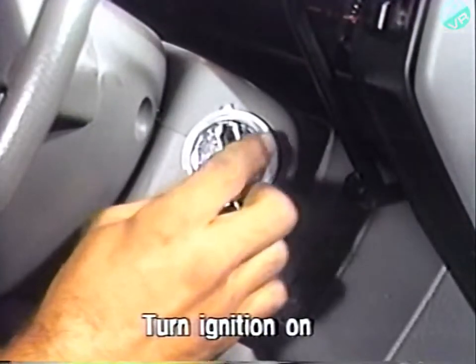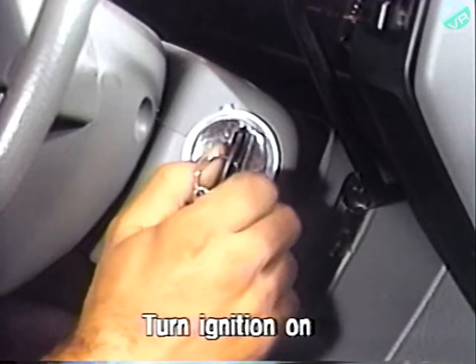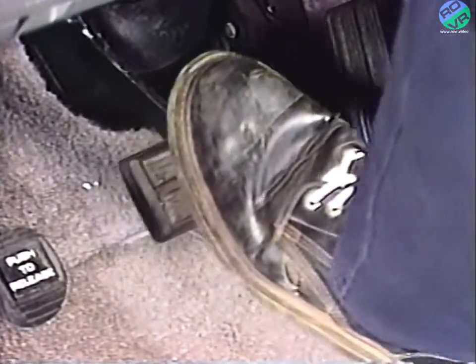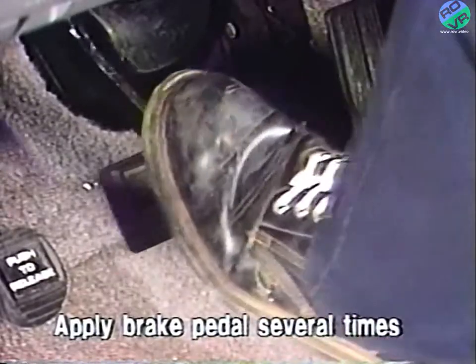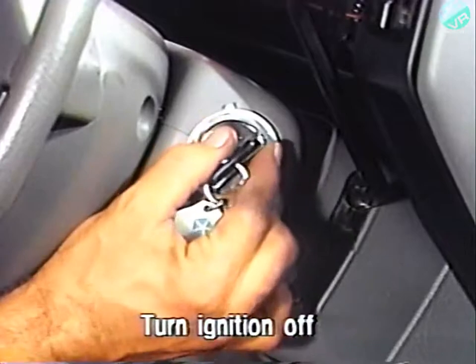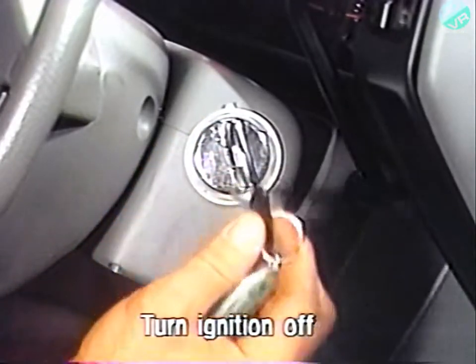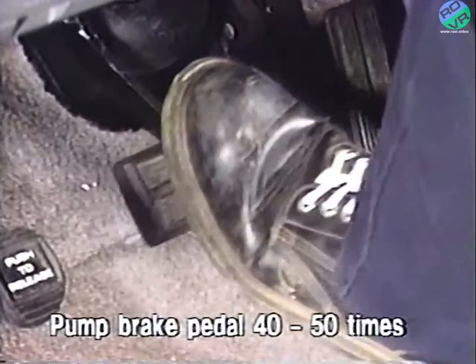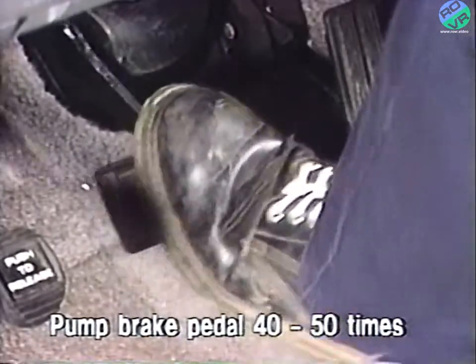Next, turn the ignition switch to the on position to start the brake booster pump, and apply the brake pedal several times to distribute the fluid. Next, turn the ignition off and pump the brake pedal 40 to 50 times until the pedal is hard.